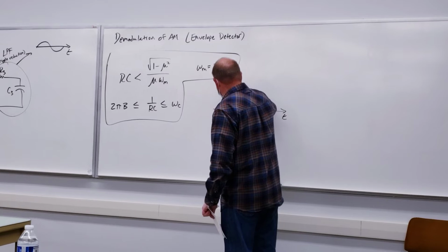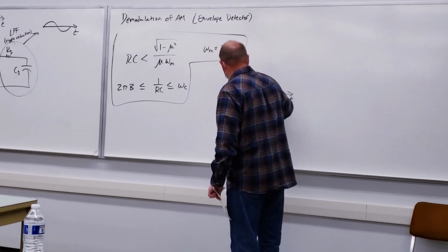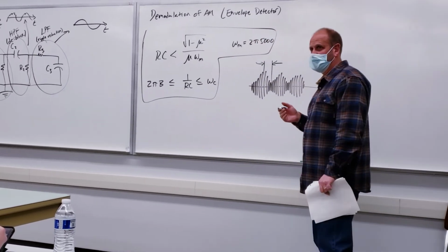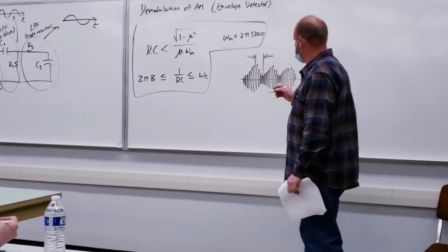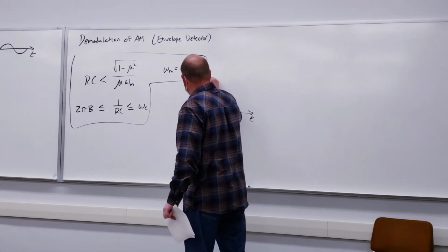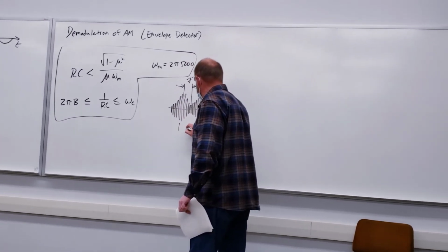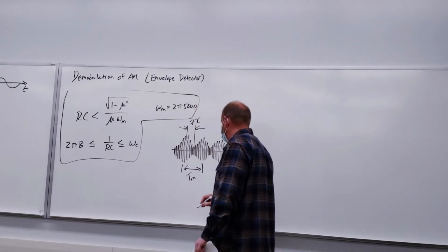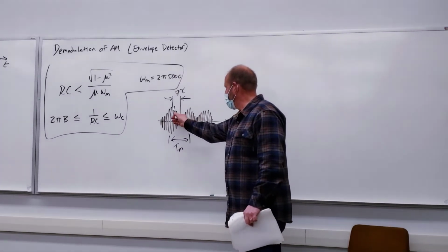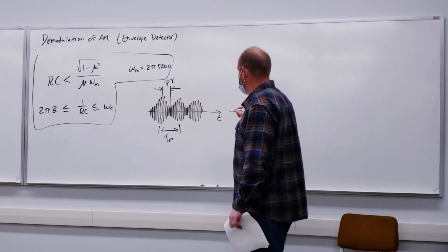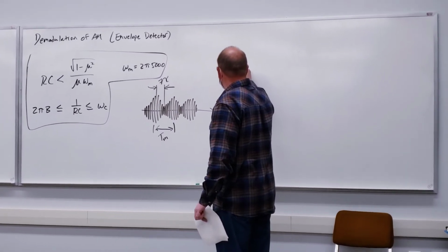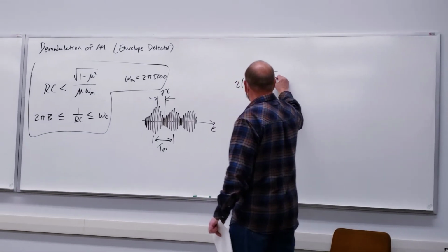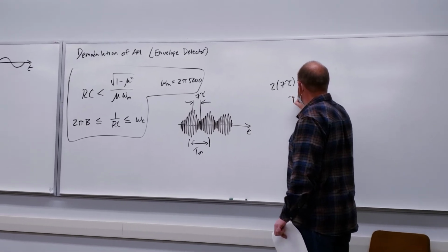If we take this peak here and the trough, then we know that a transient dies out in about 5 to 7 tau. So if I say I'm going to make that 7 tau, and I know the period of the message, across from peak to peak of the envelope, then there are 2 7 taus in one period, and then you can solve for tau.